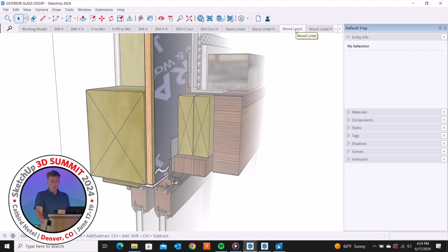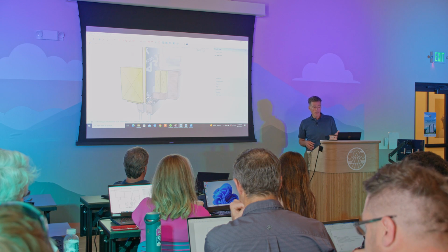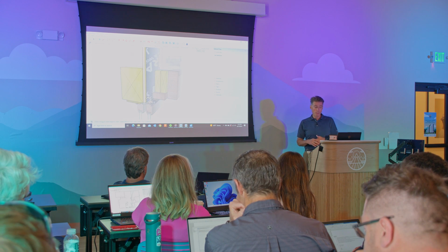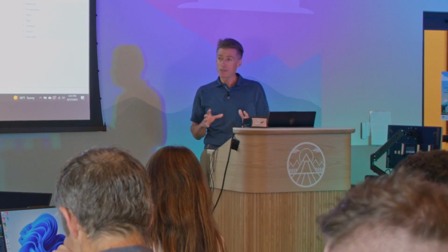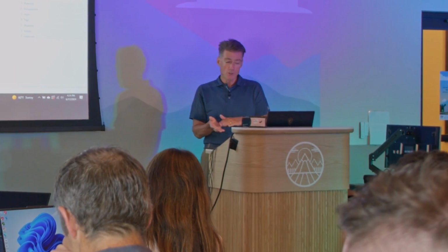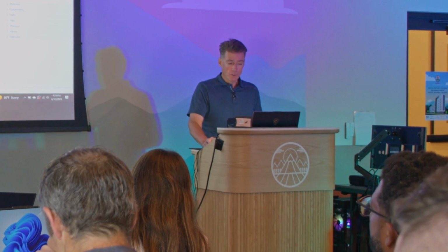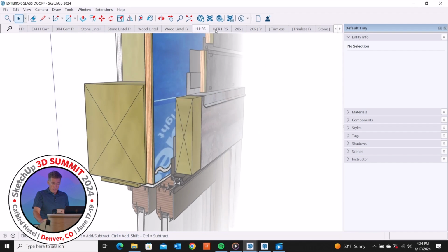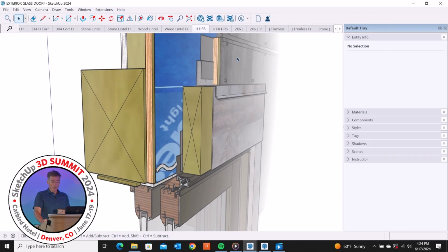And so there's one for the French door. And you can see it just continues on. In this case, it's a detail where we're doing what looks like a timber lintel in a stone veneer. And so it shows how that's packed out to a larger member and how the bottom is finished. So it still looks like a stone wood piece supporting. There's one for the French door. And you can see this goes on and on. These are all just the head details. This is in a case where we're using hot rolled steel.